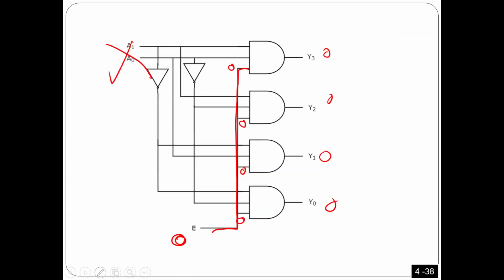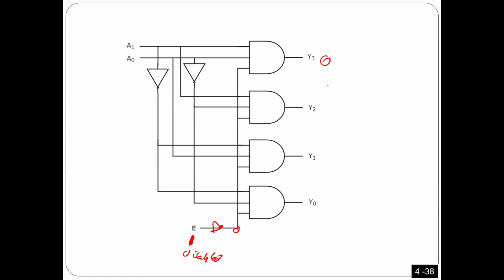And what I have to do here is very simple. I'm just going to add an inverter here. That's it. Okay? So when I put 1 here, it means it is disabled. The inverter will output 0, so all of them are zeros and it is disabled. You got what I'm saying? But if I put 0, which means enabled, the inverter output becomes 1.